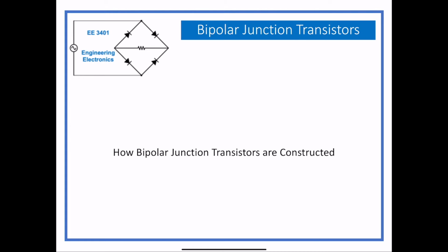The difference between MOSFETs and BJTs, the big difference, is that with a MOSFET, you have no interaction between what's at the input in DC and what's at the output. So in other words, since there's no current that goes into the gate, and it's the gate voltage that controls the output current, you have to solve the quadratic equation to find the drain current, because there's not a direct relationship between what's happening in the input. It's a little more complicated.